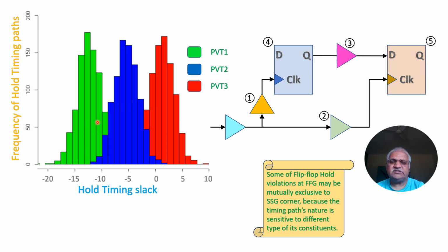So if we fix some of them, it doesn't mean that we also need to fix all of these slow corner paths. It is not necessary. If we fix one of them, the slow corner is already fixed, and vice versa. So these are some items which we need to know when we are working with the composite fashion, when all the different transistors are working together.